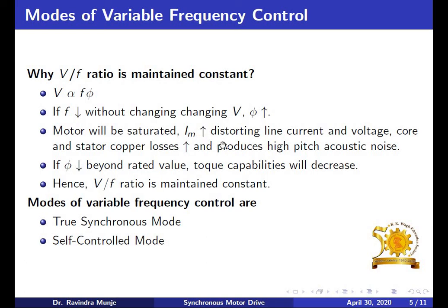Magnetizing current will increase, distorting the line current and voltage. Then because of that, core and stator copper losses increase and the motor produces high pitch acoustic noise.